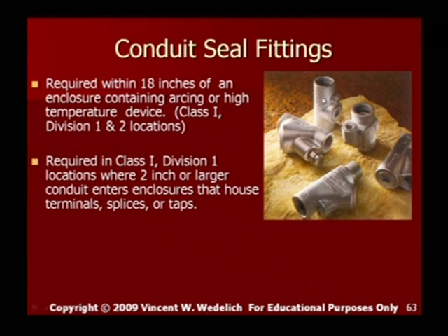And this is what a seal looks like, a conduit seal. You can see the wires allowed to pass through here, and here they have a breather drain as well. And these seals, you order them either vertical or horizontal, or you can order them where they can go vertical or horizontal. And another thing you need to know about these seals is ordinarily conduit, you fill it to 40% conduit fill, right, for wires. A standard seal can only be filled to 25%. So if you're going to follow the old 40% rule, which is a good rule, you need to buy what they call an expanded seal. So make sure you follow that. That really gets a lot of people, they get caught up on that.